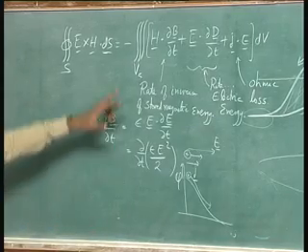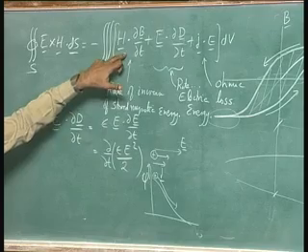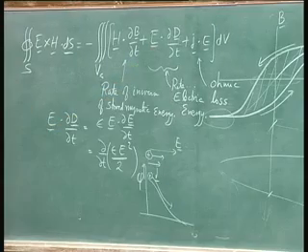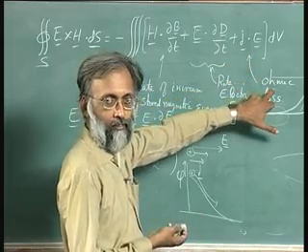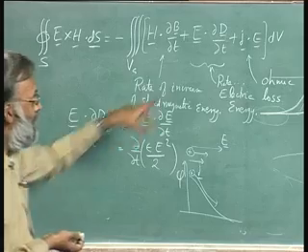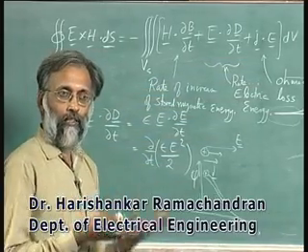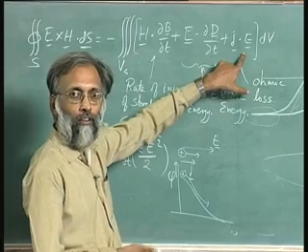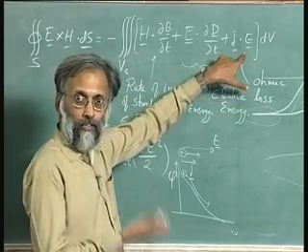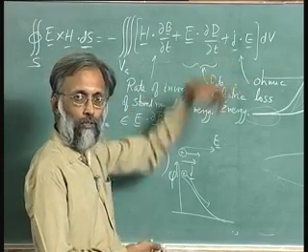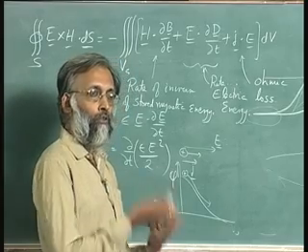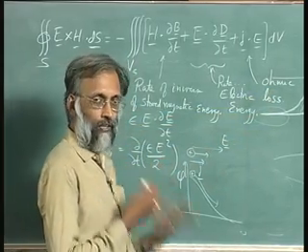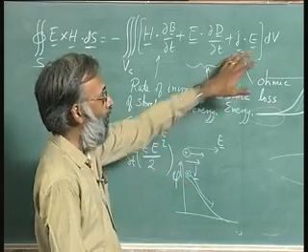So, the three terms we can see: one is the rate at which stored magnetic energy is increasing, the second is the rate at which stored electric energy is increasing, and the third is the rate at which energy is converted into heat. Now, actually it is not only energy converted into heat, because this same term can also represent energy being converted from electrical to mechanical energy. If you have a motor, this J dot E term would represent the work being done to turn the motor's axle. If it were a generator, you would have a negative term here, and J dot E would represent energy coming into the field due to the mechanical energy. So, J dot E does not represent only ohmic loss, it represents any kind of conversion to or from non-electromagnetic energy.